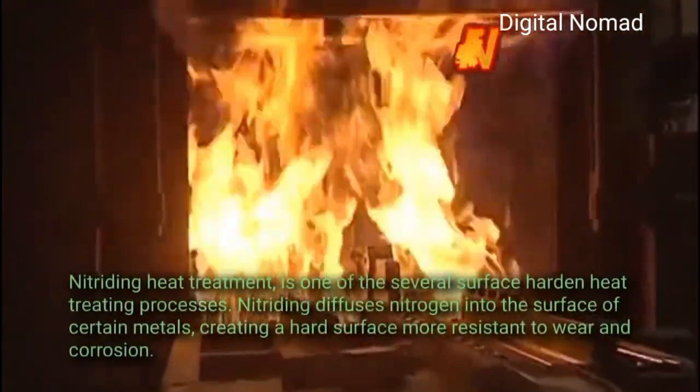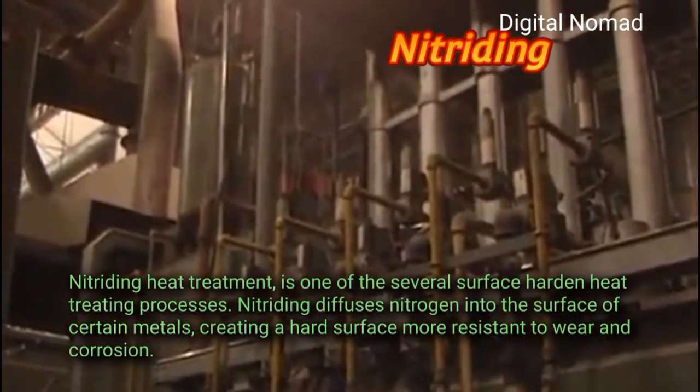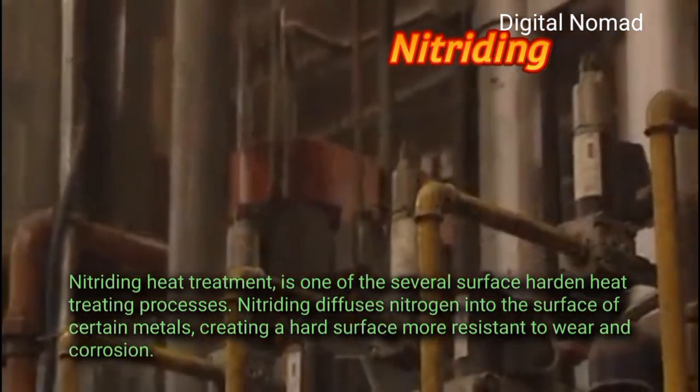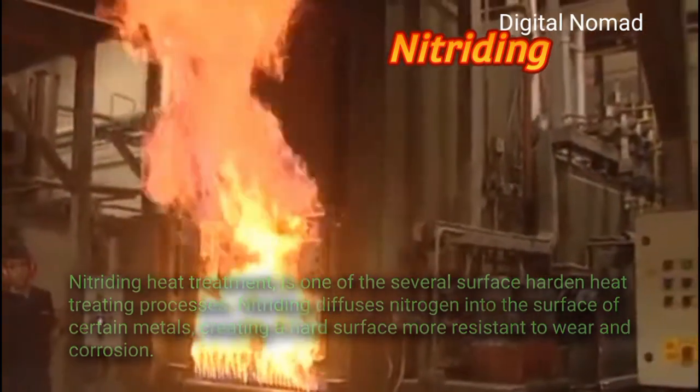Nitriding. Nitriding heat treatment is one of the several surface hardening heat treatment processes. Nitriding diffuses nitrogen into the surface of certain metals, creating a hard surface more resistant to wear and corrosion.